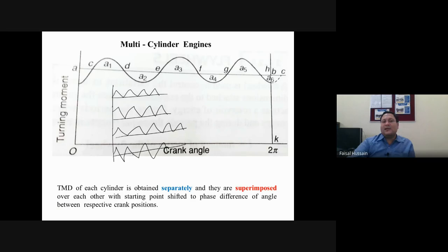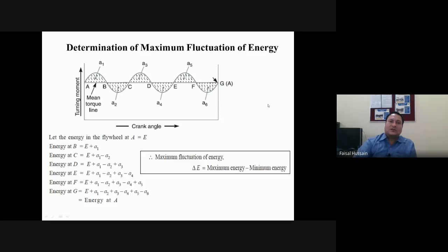So there are four cylinders. By using the phase difference, I will superimpose all these turning moment diagrams into a single turning moment diagram like this. Okay, so this is the multi-cylinder engine concept.